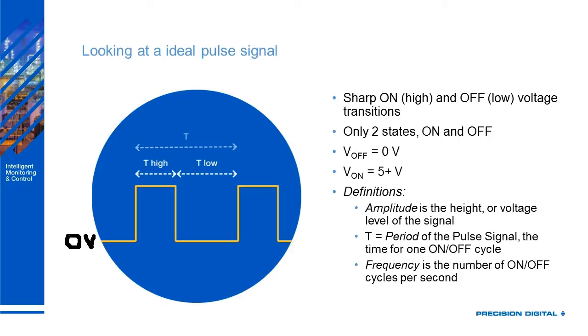And then something's going to happen in the electronics, and it's going to register a pulse, and it's going to generate for me a 5-volt transition. Now, I put 5 volts here. That realistically could be, for the purposes of an ideal signal, 24 volts. But in the ideal world, I've got a nice high voltage signal like that that's very noise immune and is a very sharp transition.